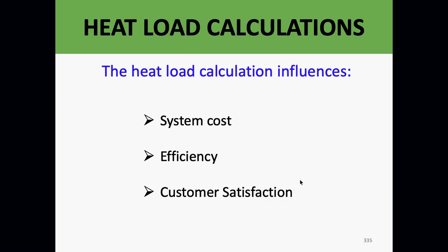Okay. So the heat load calculation influences the system cost, the efficiency, and quite honestly, most important, the customer satisfaction. A properly designed system, you will get 0 complaint calls on. Okay, if the system is not properly designed, there's going to be hot and cold spaces. Now, the best systems have a higher cost.